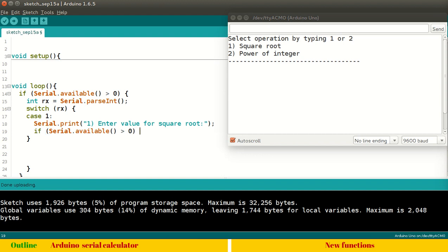And remember, after serial.available is greater than 0 and we received a Serial.parseInt, the serial buffer gets cleared. Same with the read function. The moment you read 1 byte, the serial buffer gets cleared. So it's important. It has a timeout, I guess. It's important you grab all the data at once, otherwise you will be losing serial data for